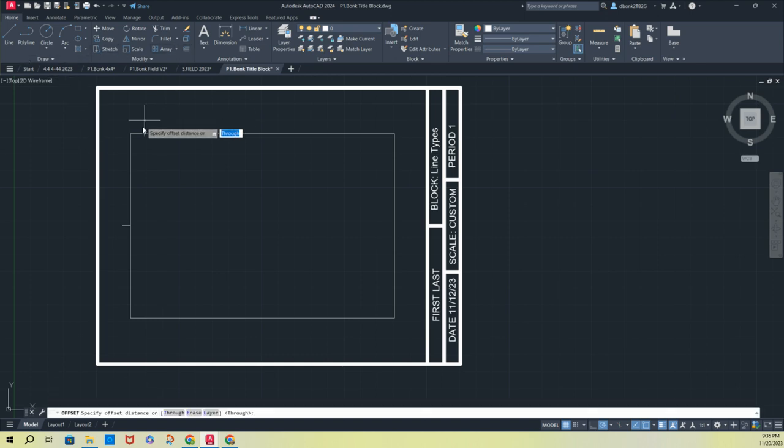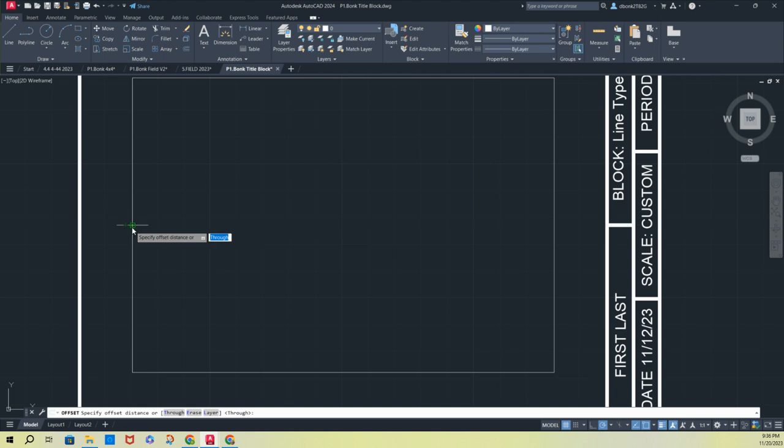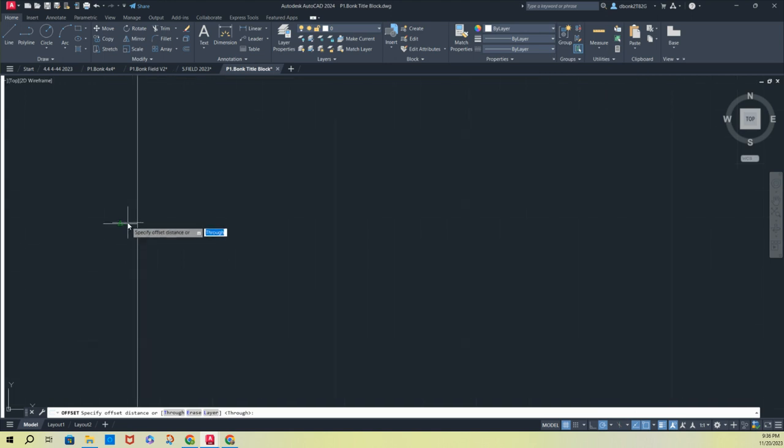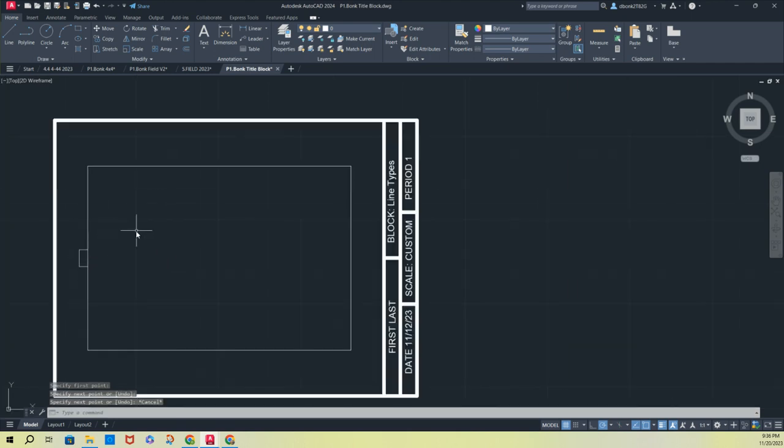Excuse me, the offset button, clicking it, click like 3 times, go to offset 1/4 of an inch, 1/4, hit enter in both directions, 1/4, enter, hit the escape key, click the middle line, delete, and then connect those two like this. Escape. So what we're going to do is we're going to draw half the field and mirror it to the other half. So you'll see it's really not that much work.